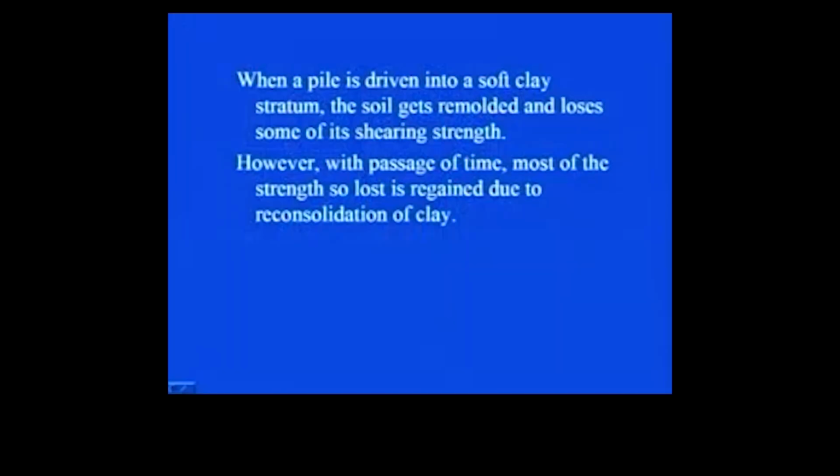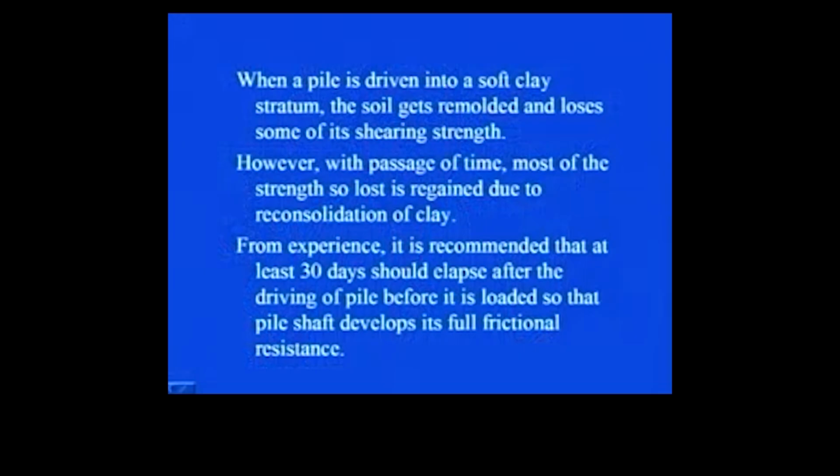However, with passage of time, most of the strength so lost is regained due to reconsolidation of clay. You know that in clay the consolidation is the predominant phenomenon. So, with the passage of time, this loss in the shear strength of the clay will be regained due to reconsolidation of clay. So, from experience it is recommended that at least 30 days should elapse after the driving of pile before it is loaded, so that pile shaft develops its full frictional resistance.